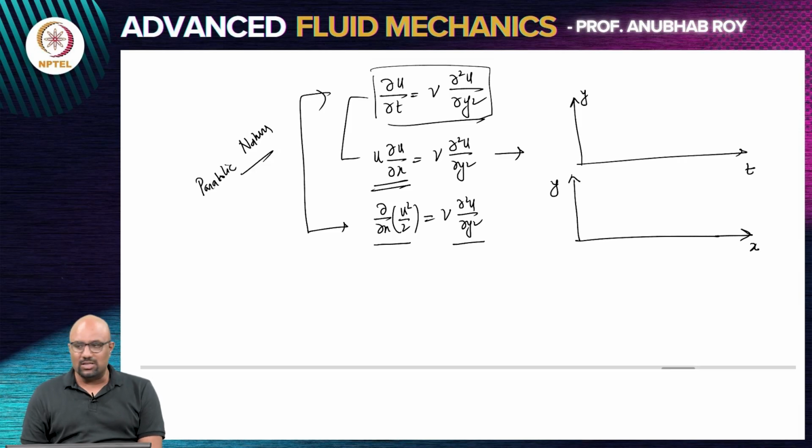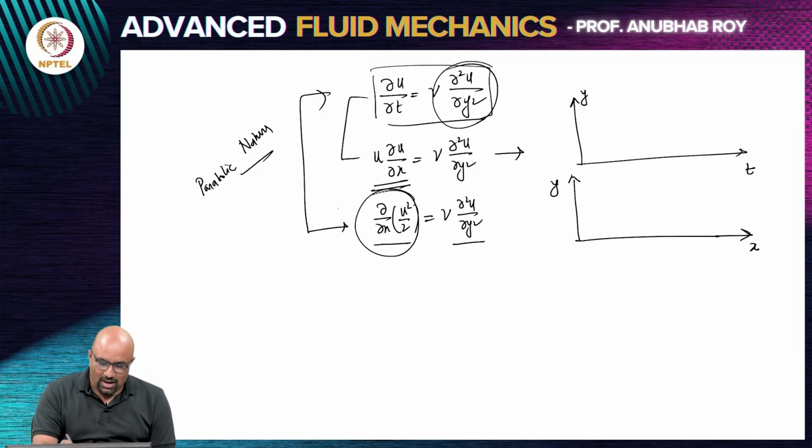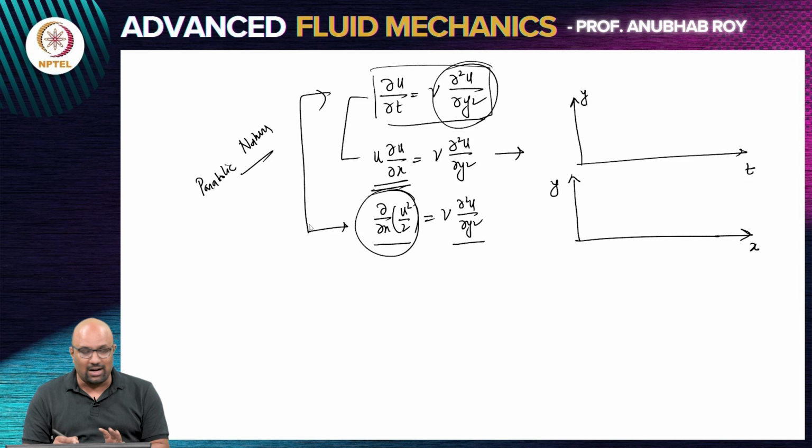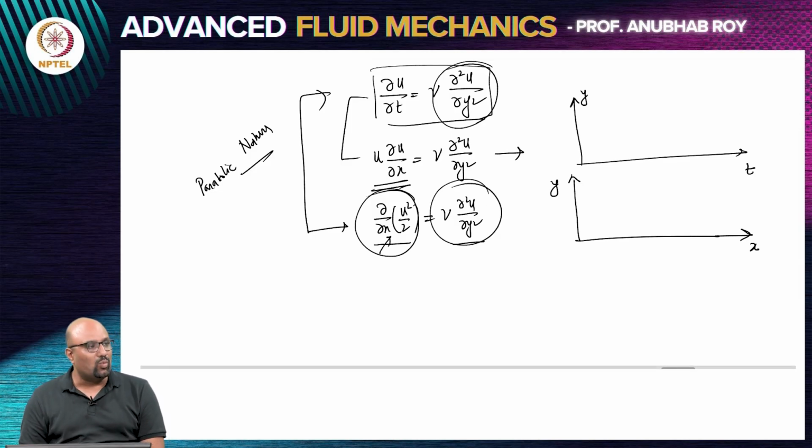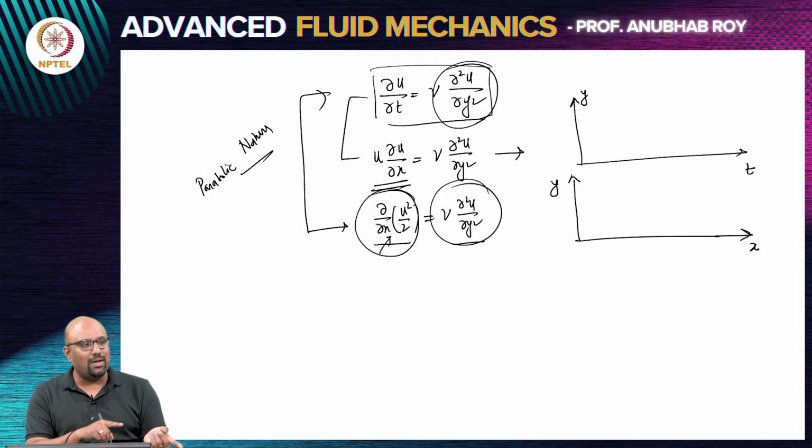The heat equation is basically a parabolic equation. So you have an evolution in a variable, or an initial value problem in a variable, with boundary conditions applied in another variable. Similarly here, you are going to think of this cartoon problem that I have written down as an evolution in one coordinate, which is x, with boundary conditions applied in y. A lot of things that we have done, you can also start thinking of in terms of a mapping of time with the x coordinate, the flow coordinate.